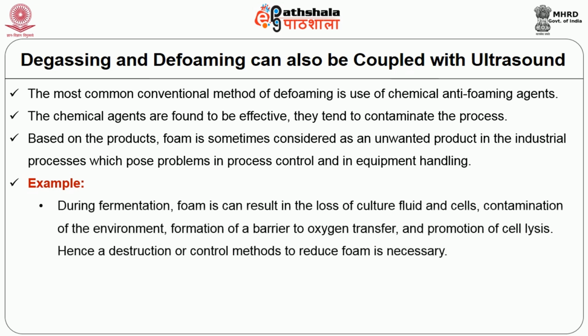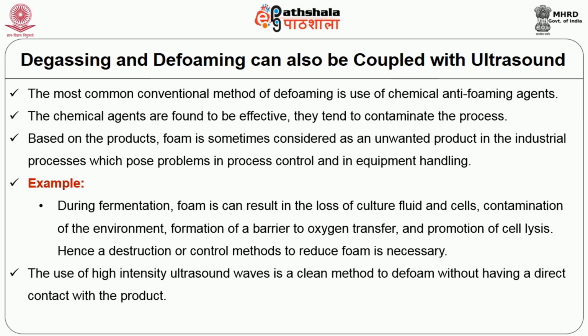For example, during fermentation, foam can result in the loss of culture fluid and cells, contamination of the environment, formation of a barrier to oxygen transfer and promotion of cell lysis. Hence, destruction or control methods to reduce foam are necessary. The use of high intensity ultrasound waves is a clean method to defoam without having a direct contact with the product.